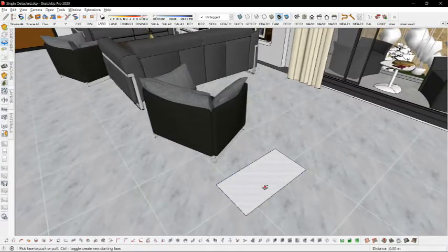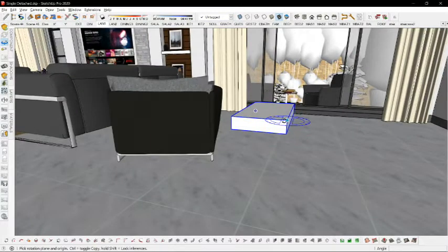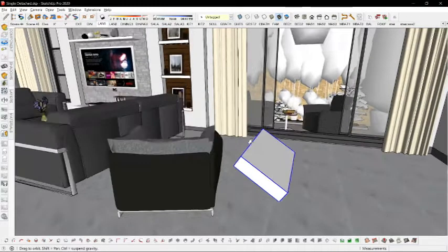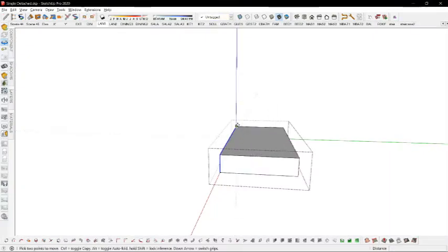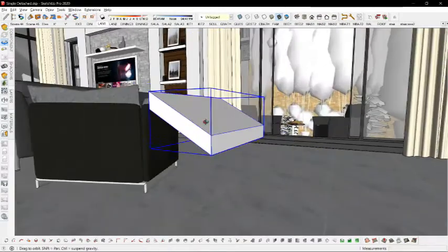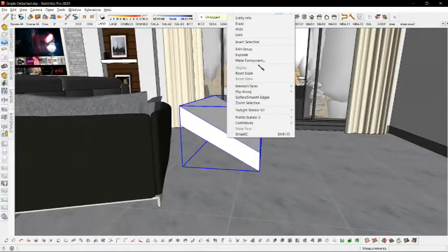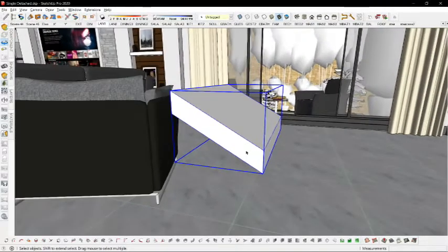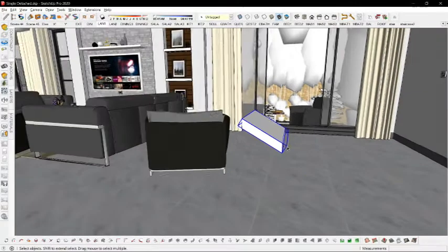That's why sometimes when we model roofs and we tilt them, you could stretch them along its own axis. However, if we use this method to tilt them, it doesn't scale along its own axis, but the axis of the world, or the model. So in cases where this happens, and it wants to be a component with different axes, you can make it a component and change the axis, relocate it. So the next time, it goes on a new axis and does not follow the world axis.